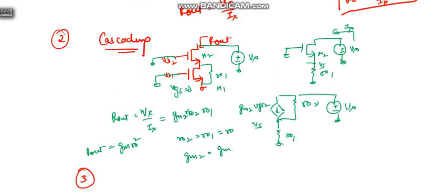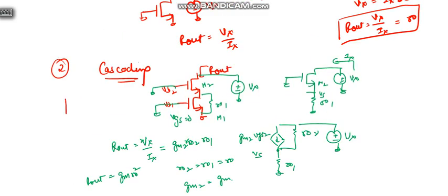Before going to cascoding of three devices, we can say that here this is, say, an intrinsic gain, and we need to find Rout, and say this is some RS. So this is the drain side, and this is gain A. This is not actually gain A, this is basically 1 by A. So in cascoding, when we see from the drain side, basically this is an attenuator.